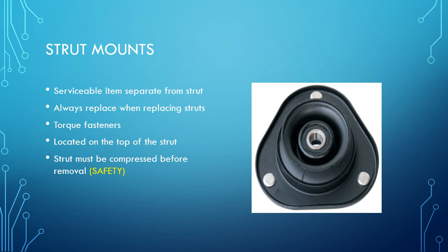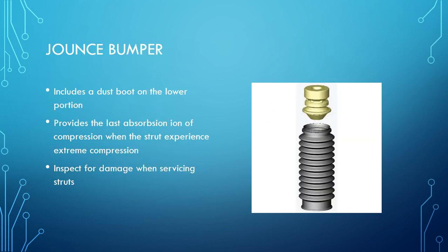Strut must be compressed before removal. This is a safety noted item. You never, ever try to remove the center collar nut without decompressing the springs. These springs are very, very dangerous. They're very, very well compressed within that strut unit or the suspension for that matter. So you must always look up the service procedure and be aware of the proper way to decompress or remove a spring or a strut prior to removing any securing anchors or nuts. I remind you, this is a safety requirement.